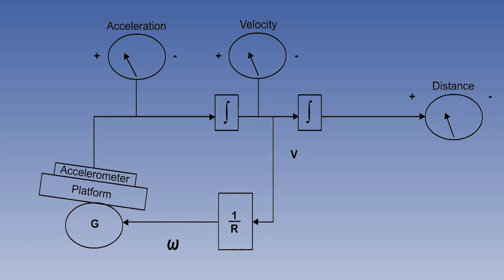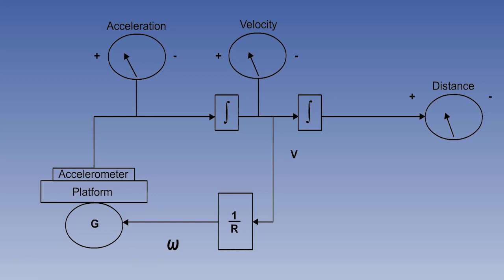The system can't tell that we are still on chocks, and this is a false velocity, so it assumes that the aircraft is travelling around the curvature of the Earth, and slowly brings the platform to the level, which means that the source of the false acceleration is removed. You might think that this has solved the problem. The platform is now level, and there is no false acceleration.